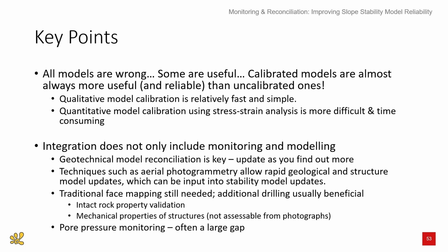Integration doesn't only include monitoring and modeling. Geotechnical model reconciliation is key. So as you progress excavations, you have a lot of opportunity, especially with improving technologies such as photogrammetry and laser scanning, to rapidly assess geological and structure conditions and update the models as you go.